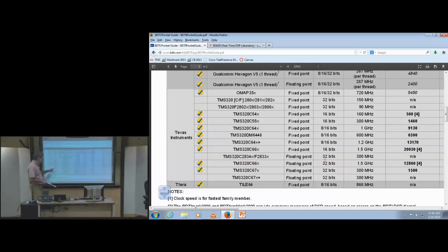But if you look at the numbers, they really come into 3 groupings. There's the 2000 family, 5000 family, and the 6000 family. And the rest of these are really subfamilies within those 3 main families. So the 2000 is mainly DSP and control put together. It's also used in smart grid communications, power line communications, for example. This is the old 2G cell phone, also digital still cameras, C5000. And C6000 is everything else. And actually the smart grid stuff is the 2833 family down here.